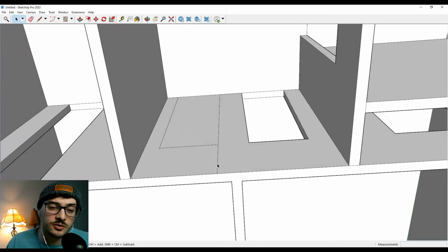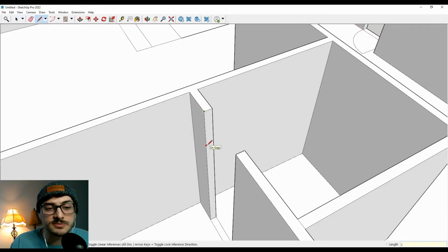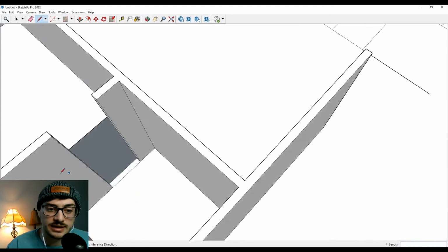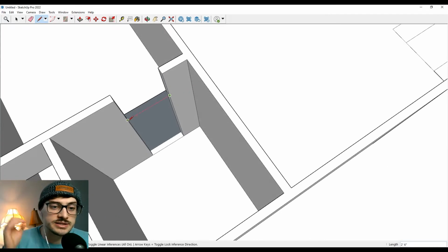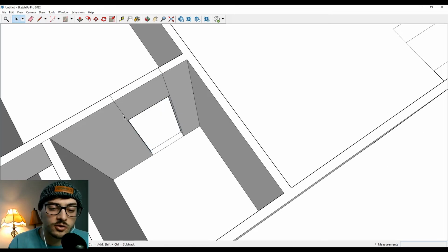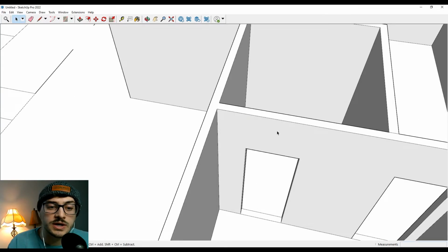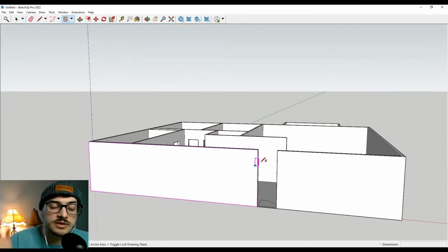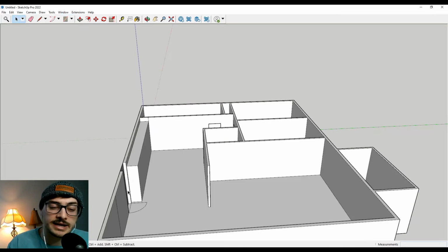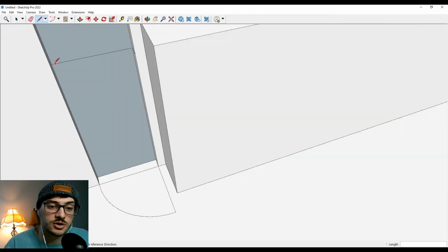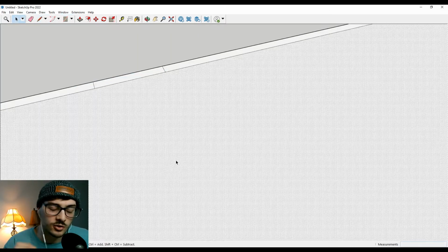Once you have it fully extruded, you need to go back and do some detailed work. Like if you defined, like I do, doorways in your 2D model and show on the floor plan where each doorway goes, then once you extrude and the doors aren't included, you need to go back and add the ceiling structure over the floor plan, over the doorways.